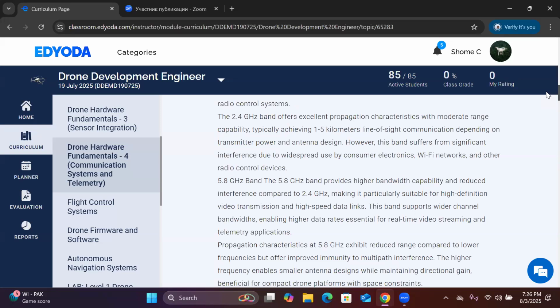Accordingly, there is an RF power calculation on a logarithmic level, how we can add the different power components with respect to dB and dBm. And finally, we can get the watt or the RF power output corresponding to a range of 50 kilometer. So in that way, we need to tune the RF power amplifier circuitry, because the wireless LAN module that is purchased from a certain manufacturer or supplier is capable of transmitting the RF power only till a certain limit. It cannot go beyond that. So in order to extend the RF power capability, we need to add additional RF power amplifier blocks. Okay.